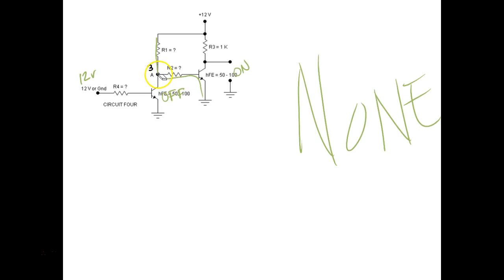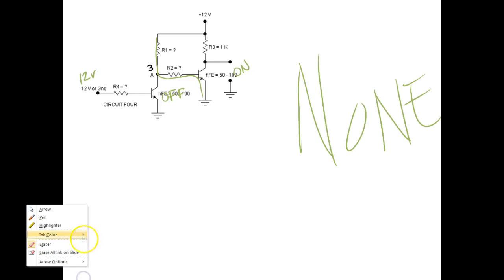The only way I could put 0 volts right there, well, we've got to put less than 7/10 of a volt, or less than 500 millivolts, to turn it off. If we put 0 volts there, we're guaranteed to turn it off. So what I'm doing, guys, is I'm coming over here and doing this.